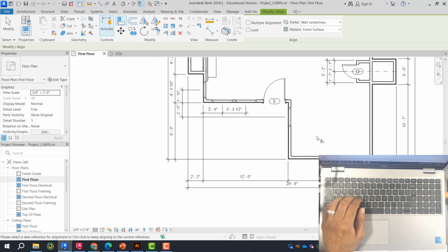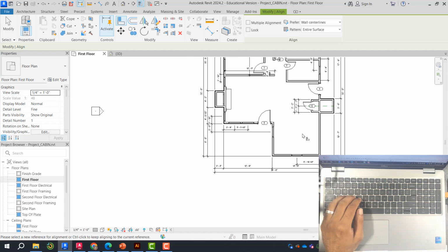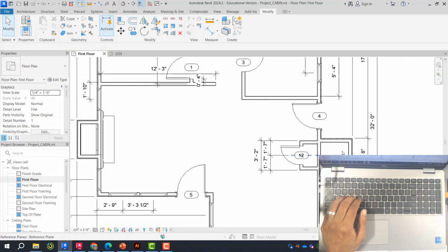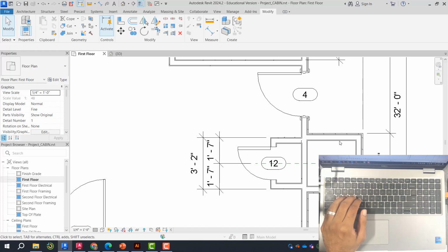Next, we're going to take a look at what our doors and window headers are doing. One of the things that I missed in my last video was to add a door to the water heater, and we're going to simply add this door with the window in it over here. That door in particular is going to be 2 feet wide, and I want it to swing outwards.